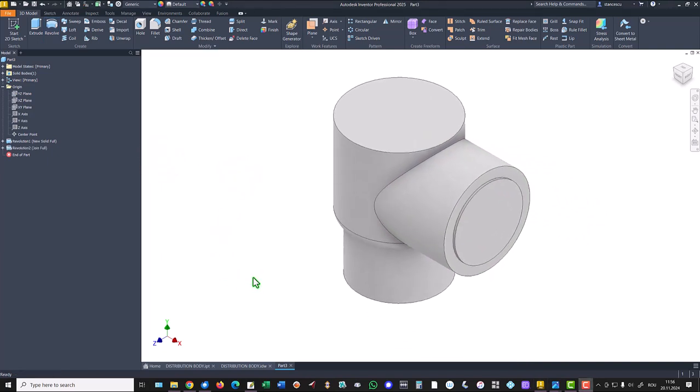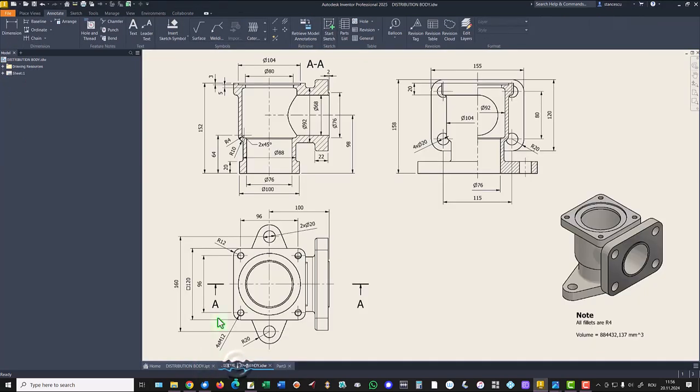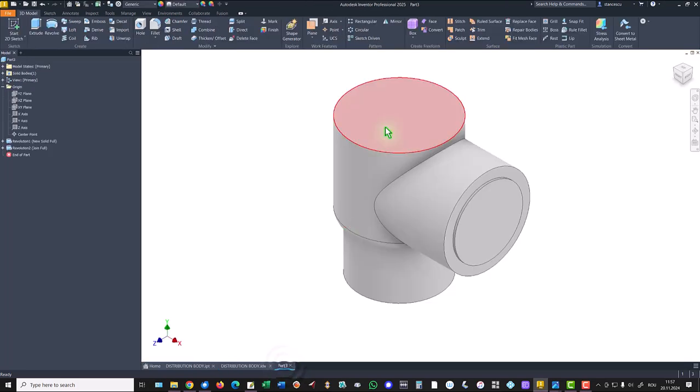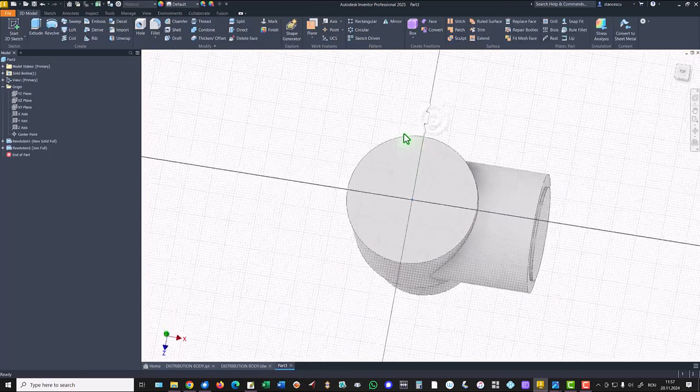Okay, we continue with this flange 120, a square 120, radius 12, placed at a distance of 152, the level we know, and the thickness of 20. Good. We use this plane.